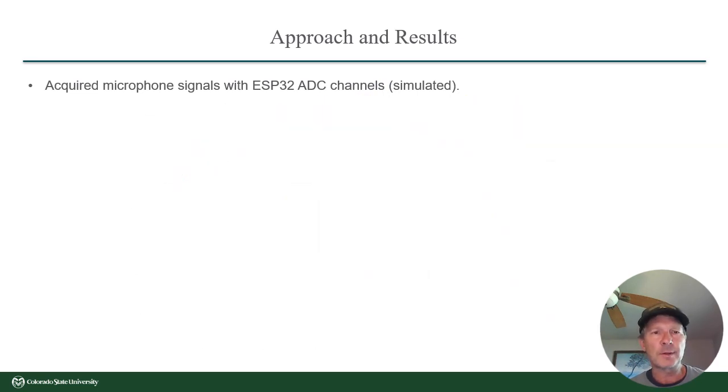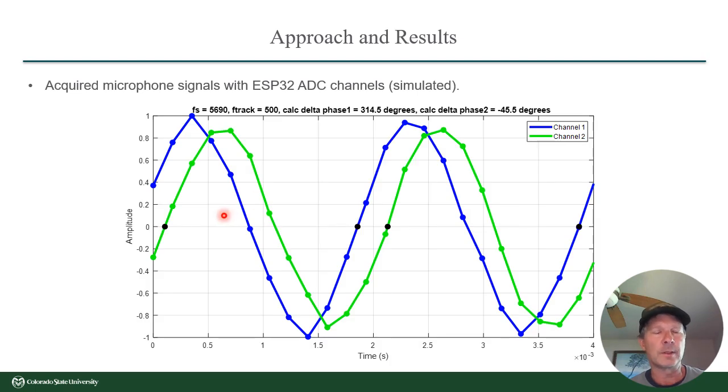And so there's another case where if the phase is such that channel 1, the blue channel here, its first zero cross doesn't come until after the first zero cross of channel 2, then the phase is the difference between these first samples, and so it looks much bigger than it is. We really want this 45 degrees here, but what we're getting is this big phase shift here.